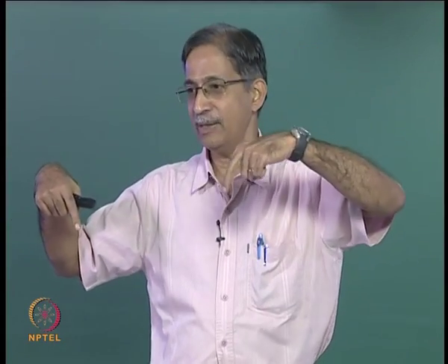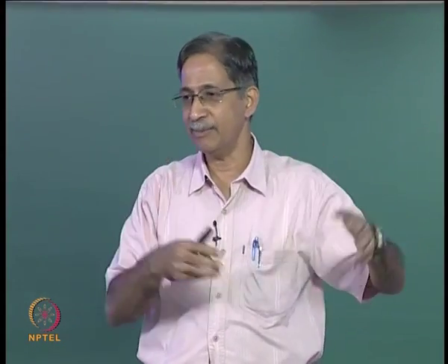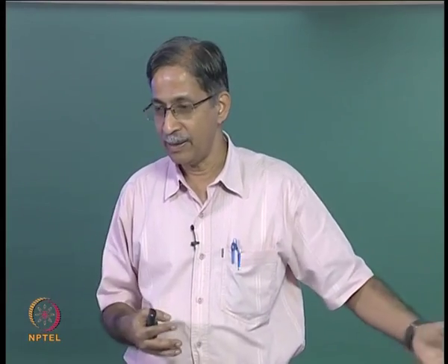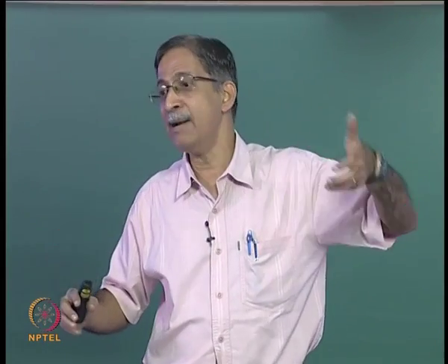Why do we want to do this? Because we really want to find out what is happening to our 4EI by L, 2EI by L, 3EI by L. That is our real interest. We are now in a position to do that, because in the previous case we looked at a beam with an axial force P and some loading acting on it, and we said if it is concentrated, it is something, if it is UDL, it is something, we can work it out. Now we do not put those loads, we apply an end moment.